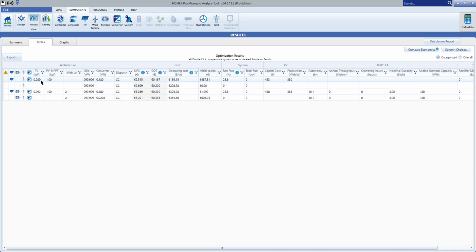So the cheapest scenario is the first line right now, with a PV module and connected to the grid with no battery system, and also an inverter that we need. The PV panel in this example will be 290 watts, which of course is maybe 1 or 2 modules, so it's not much, but it's just to have some renewable energy in the system.